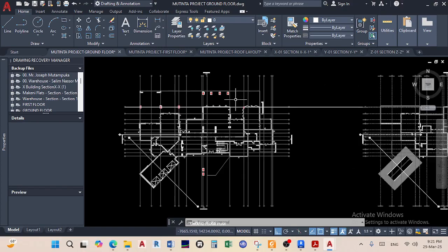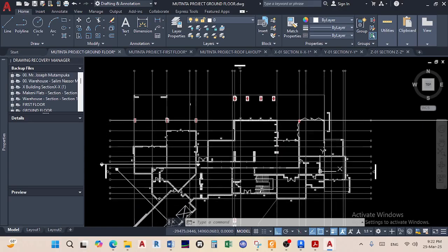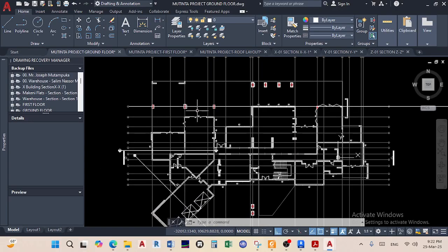So now moving on, we need identification because column placement can only happen once. And if you've got the time, you can actually start from Revit and then take it to Protastructure. Or since we've already started in AutoCAD, there's another way. According to my workflow, I can move from AutoCAD to Prota, or I can move from Revit to Prota. Either one can work because Revit also can output a DWG and a DXF file, and using that you can import it in Prota.